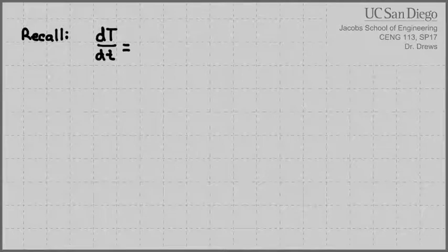If you remember your energy balance from the batch reactor, it had about 3 components in it. The 3 components were trying to describe how temperature changes with time, the temperature trajectory. The 3 things that could impact how temperature changes with time started with a Q dot term. The Q dot term said if I dump energy into the system or take energy out, usually by wrapping it in another fluid, then if I wrap the entire reactor in a hot fluid, I can add energy to the system. If I wrap it in a cold fluid, I can remove energy from the system. That was our Q term. And then we were exposed to this other term, which was V times RA delta H.